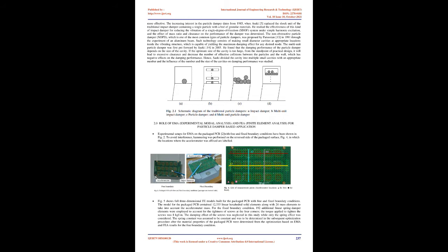The multi-unit particle damper was first put forward by Saeki [14] in 2005. He found that the damping performance of the particle damper depends on the size of the cavity. If the optimum size of the cavity is too large, from the standpoint of practical design, it will lead to excessive clearance and decrease the number of effective collisions between the particles and the wall, which has negative effects on the damping performance. Hence, Saeki divided the cavity into multiple small cavities with an appropriate number, and the influence of the number and the size of the cavities on damping performance was studied.